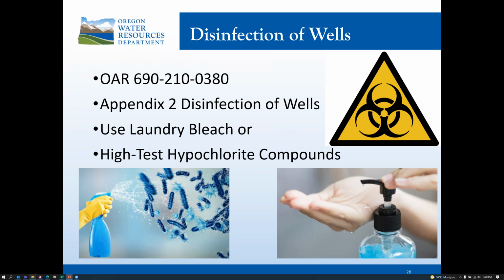So again, when we talk about disinfection of wells, the applicable OAR is 692-010-0380. Appendix 2 details the disinfection of wells, and you need to use either laundry bleach or high test hypochlorite compounds.